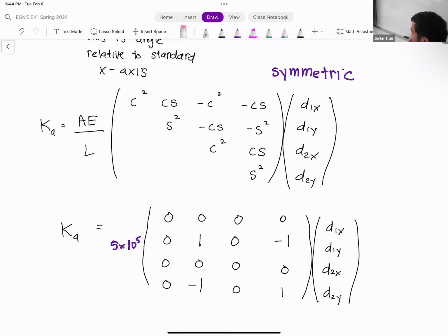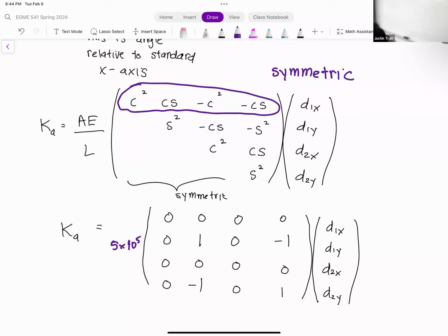Okay. So I've gone ahead and deleted that lower half, because what we know, based on what we've just seen, is that this part here is symmetric. And so when you're computing this element stiffness matrix, I would go row for row, but as you write in the rows, you can then reflect it down into their respective column, reflecting across that ham sandwich line, right? Let's say that you start with this first row here. The first row is always the first one you compute. After you compute that first row, you can slide into their mirror image locations right there, okay? So usually what I tell students is that you should write the row and then reflect it into the column, row and then column, okay? So the first row slides into the first column just like that. You can imagine a clock hand moving down like that, okay?